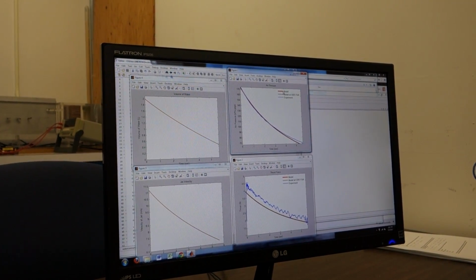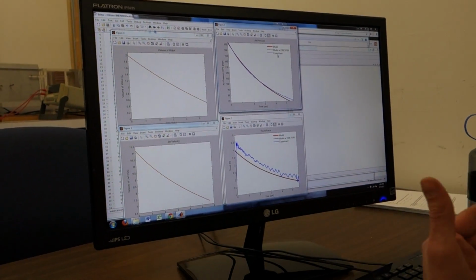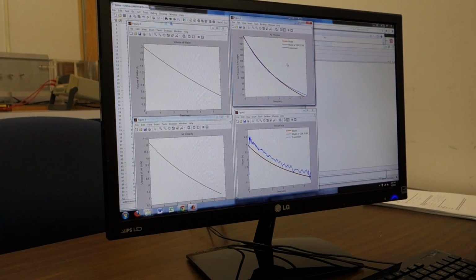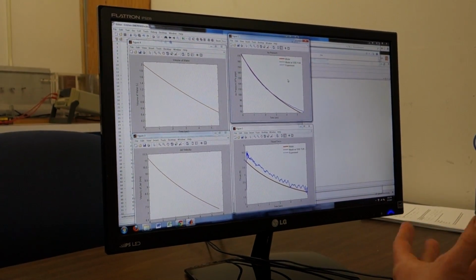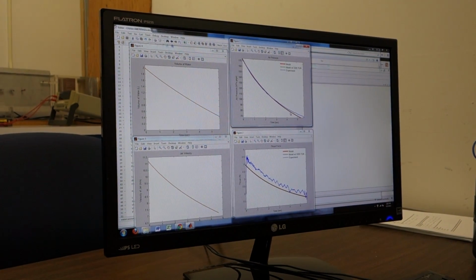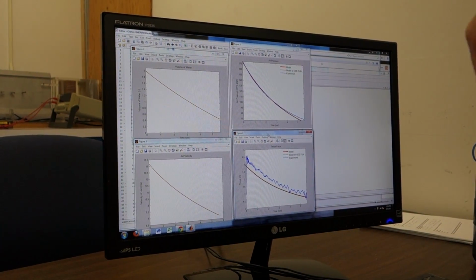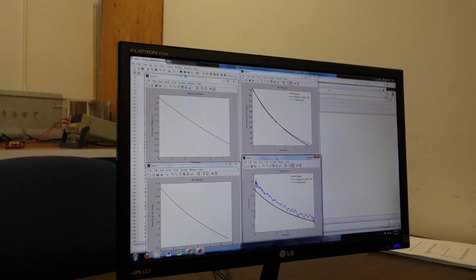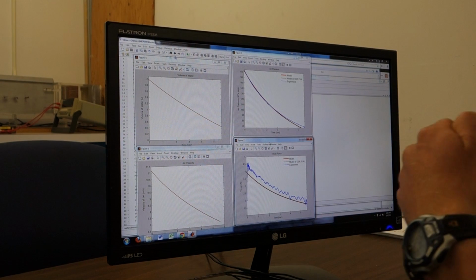The difference between the red and the black model is that the black line is the analytical model using MATLAB's ODE45 function, which uses a higher order finite difference scheme, which will be better at approximating the derivative, but they're pretty much identical. So that will be a good thing to have if we have extra time in the lab. If you want to work on getting ODE45 set up instead of doing the forward difference scheme yourself, that would be a good practice, a good thing to do.